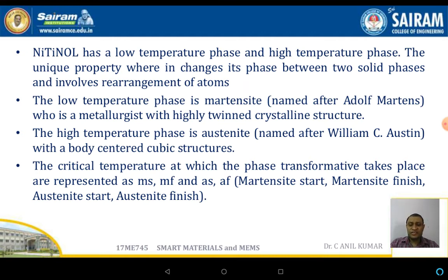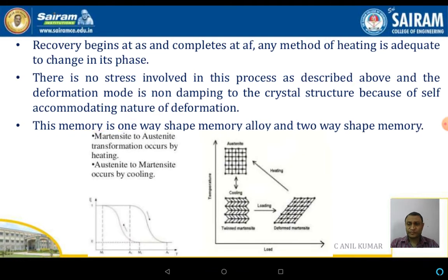These are the stages in the loading condition with respect to nitinol, or any shape memory alloy. The martensite phase is with respect to the loading condition. The austenite phase is at the thermal stage, or the temperature condition. Now, the recovery begins at A_s and completes at austenite finish.